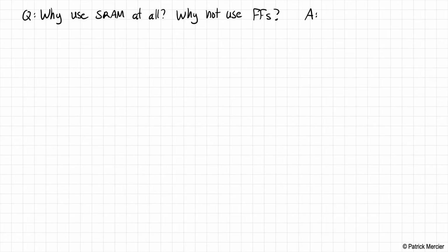So the answer, and it's a very simple answer and one that we've actually alluded to already before, is density. Okay, flip-flops are not super dense. You need lots of transistors to store 1 bit of information in a flip-flop. An SRAM only requires 6. Now, of course, there's overhead from the column and the row circuits and the sense amplifiers and so on, but if you build a large enough array, those get amortized out effectively. All right. So I would argue that, and everybody would argue, that the reason we use SRAM instead of flip-flops for large data storage reasons is for density purposes.